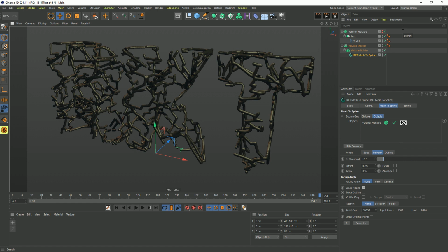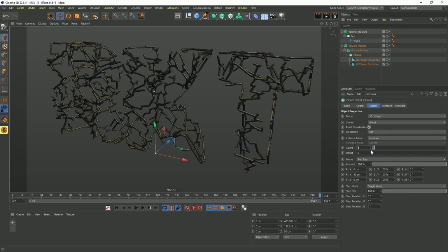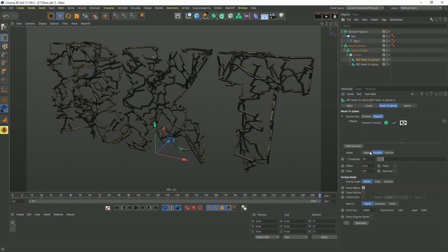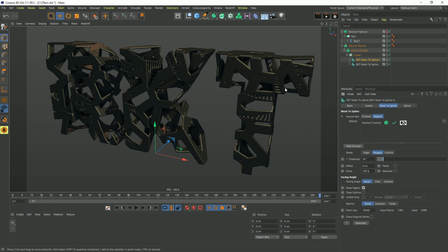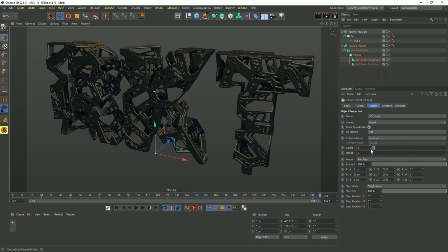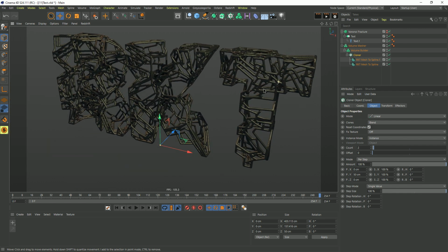And then combining that even further with that same cloner method, so we can put 2 different Mesh to Splines, tell the cloner to blend between them in linear mode, and give it a count of, I don't know, how about 5? So now the volume builder should be seeing this, and hopefully it is viewing it as a spline. So if I say growth on one is 100% and the other is at 0, it's transitioning between those two. I don't want quite as many segments, so I shall lower that down to something smaller. And now, yeah, we get this line traveling in between the two.